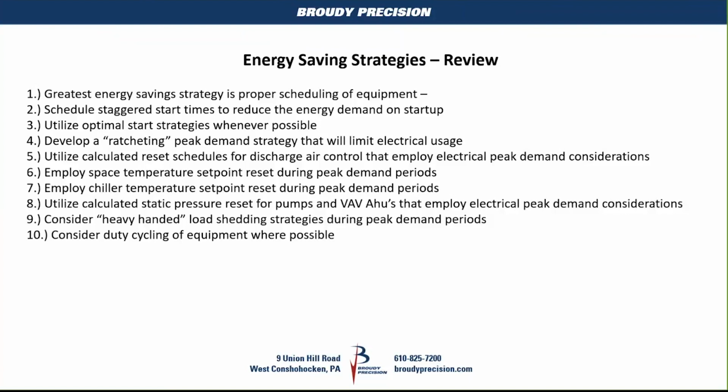You can basically take loads that you can shed and shut them off during the course of a half an hour or during the course of an hour. And you continue to shut loads off all during the daytime to prevent the increased energy usage.